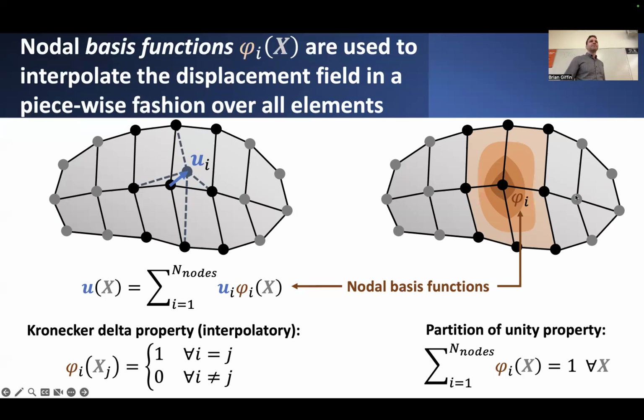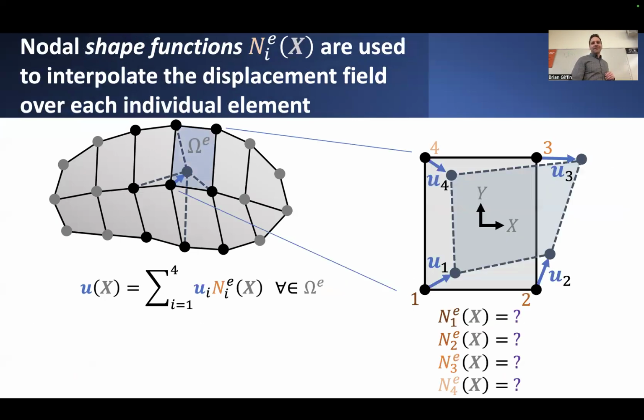That's the compact support property, which also had the added advantage of resulting in finite element stiffness matrices with banded and sparsity properties. Really nice properties for achieving good numerical efficiency. So those are finite element basis functions as they would extend into this 2D and 3D context.